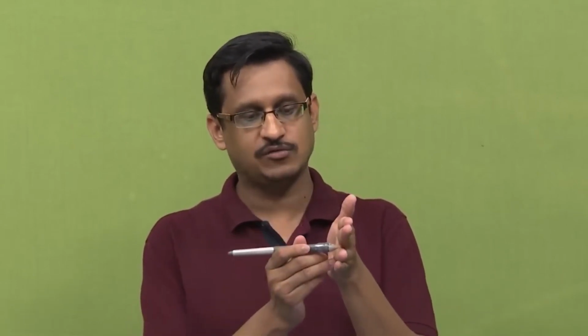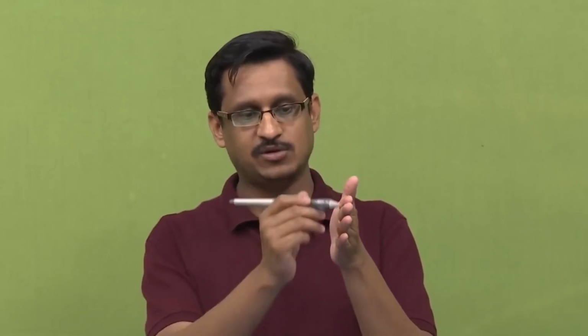There is a relationship between these two which we will see in the next module, which tells you that the direction of E cross H should point in the direction of wave propagation. So, the wave is propagating along the z axis, and at every constant value of z you have a transverse plane in x and y, and the fields are independent of x and y.